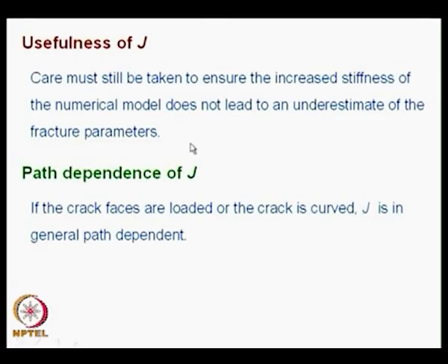So, people will do a reduced integration technique, a combination of that, they will go through the Gauss points away from the crack tip. So, there are some recommendations that you have to follow from the finite element solution developer, and based on that you will have to evaluate J. It definitely provides you, because of path independence, a freedom to select your chosen path, but also look at the integration scheme that you employ, so that the approximations of finite element do not affect your fracture calculations.